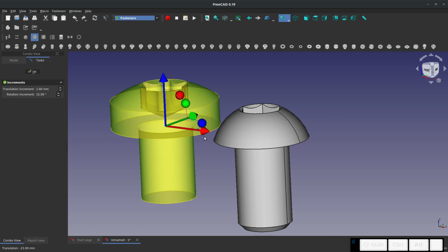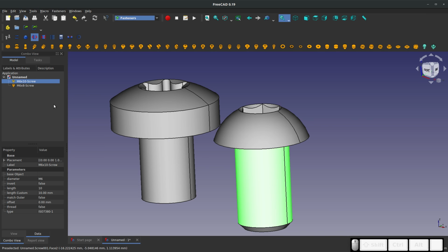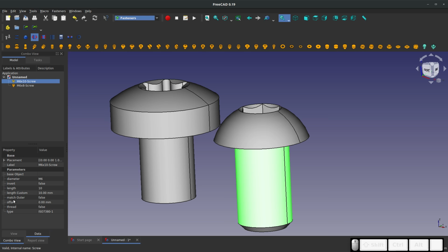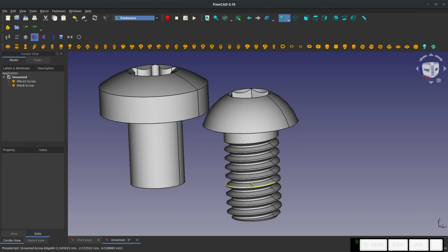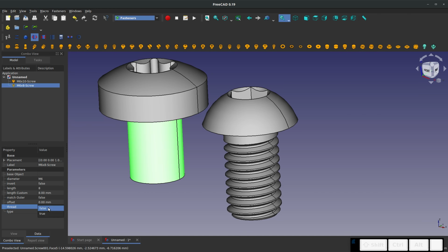And when we go to customize these fasteners, one of the really great things, people love this for 3D printing, we'll take this kind of screw and we'll actually turn the thread to true, and it gives us a very realistic screw thread. Now that's very computationally expensive to have helical features like this, so only do screw threads if you need it or your models will slow down. You can tell how much longer it is to generate this one than this last one even.